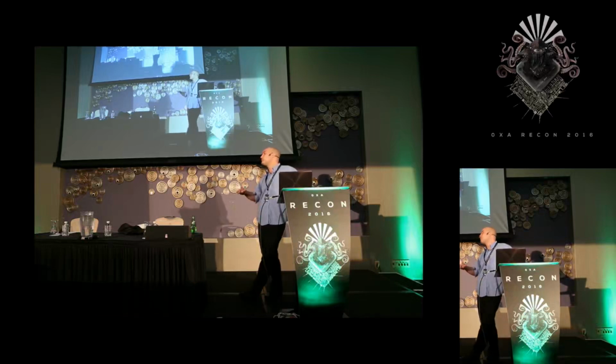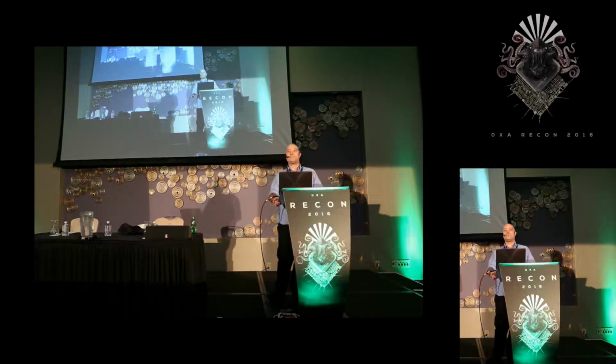For the main transport stream or for the out-of-band transport stream? Okay, for the out-of-band transport stream, I wrote some software that did the de-randomization of these things on the raw transport stream because I was getting it directly out of the QPSK demodulator. For the main transport stream, all the demodulation is done and complete before it goes into the ACP. So it looks like a normal transport stream, just encrypted. So after the software decryption, then I could feed it right into VLC. Can you just repeat the question? Sorry. Yeah, the question was if there was any processing on the transport stream that I had to do after decryption.